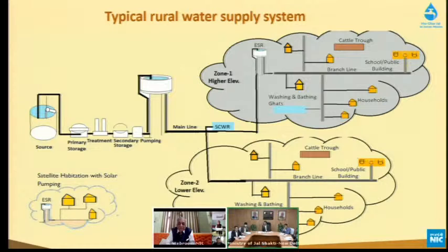So that's not how it should happen. First of all, we should know how my habitation pattern is, and if I want my flow and pressure at the end point, what will be the minimum requirement of head? Accordingly, we should decide the head, right? So as a shortcut, some places have done that, okay, now I have placed my tank, and since water is not reaching the end point, they directly lay a separate pipeline to that connection. So it's not the optimum design.